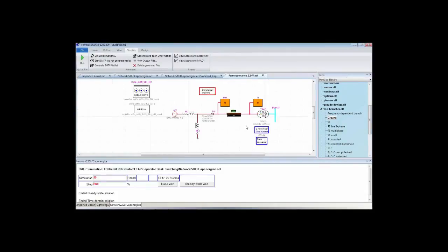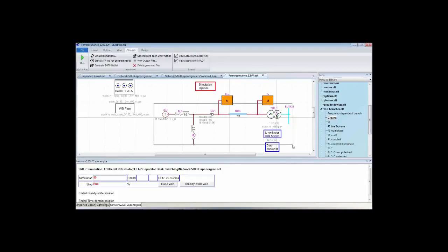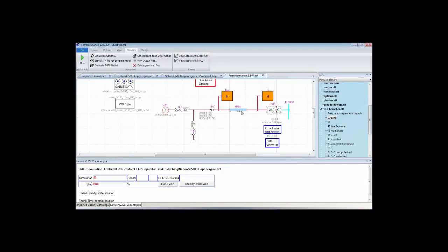So this is a case of ferroresonance here, where we model an 11 kV network. This is a distribution transformer connected to 400 meter cables. And for any reason, the breaker here didn't close. Maybe we had a mechanical problem, and one of the 3 phases didn't close. So now we'd like to run the simulation, and we are simply closing this breaker and energizing the cables on the transformers. And I can again go in scope view.